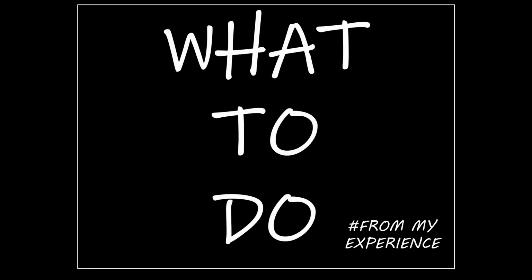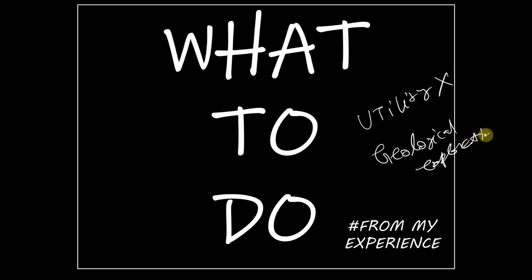So let's start. What to do on the very first day of your GPR survey. Whatever I'll be discussing is from my experience. These are the steps I generally take when I am surveying a virgin area. I will not be discussing the utility part, it's very easy. I'll only be discussing the geological exploration part. The very first step, and I'm assuming you have a 200 megahertz antenna, plus a 10 to 80 megahertz antenna.